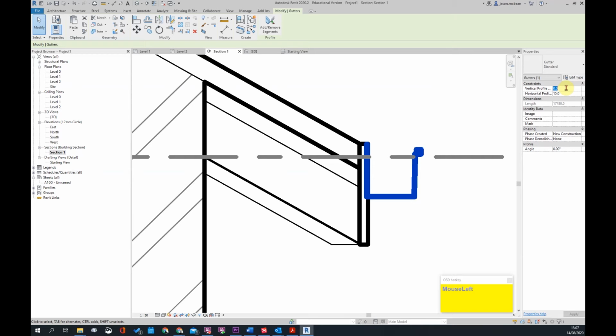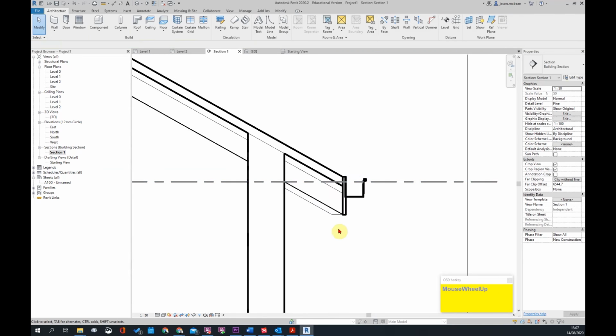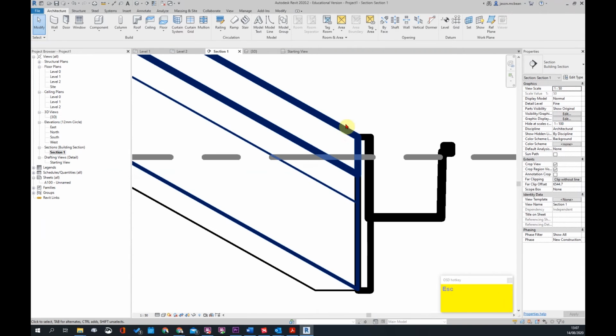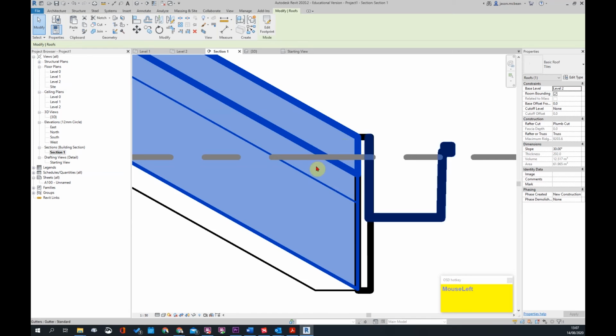Yeah, look, that timber batten will only be visible in section. It's because it's pretty much a drafted object. You don't want to go and model every batten. Trust me, it's not worth your while. So when you cut a section through, and it's an object that you never see, you never really see it other than through a section. So if you're taking 3D views and all that kind of thing, you don't model it. That's why I use Revit's families to kind of give me this information. Okay, and there's a technique, I'll show you how I draft in this.